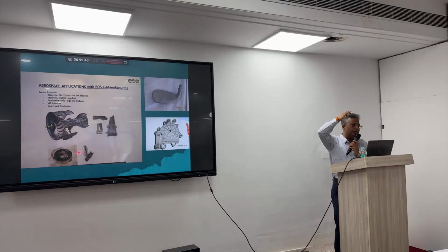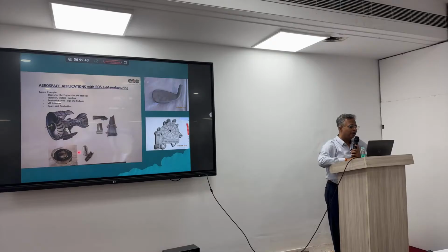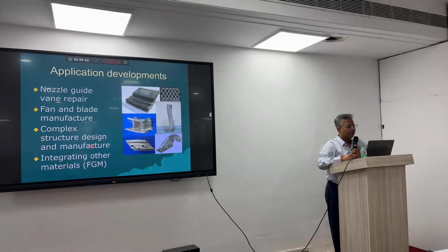So titanium aerospace grade alloy can be very well deposited, and we can make components and repair components by this method. Then there are some very typical applications which have been shown here. The component is like this, a third column, and it has some internal details also. You have these kinds of components, correct? So then what you see is that for components like this, there is no other choice other than doing additive manufacturing.